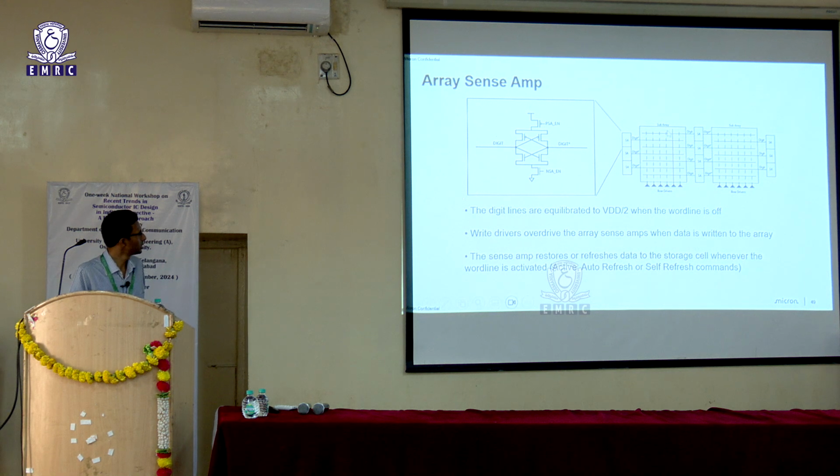And the way you organize these sense amplifiers is like this. So you have memories here, and each vertical line represents a row, and the horizontal line represents a column. You have sense amplifiers on either side. Whenever you are accessing a particular row and a particular digit line, the data from this gets altered. So if it was 0.75 earlier, it gets altered to 0.9 now, and the sense amp's other input comes from the other bank, which is not accessed.